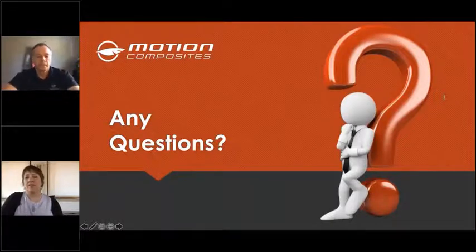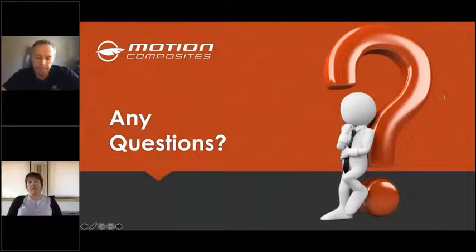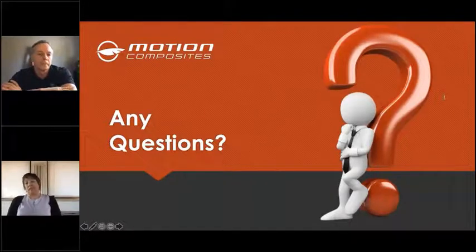Ralph, yeah, I see that question from Ralph about advantages in caster selection for use with active power assist users. So I think it depends on what type of power assist. You're right, if they're using like a SmartDrive or something like that, you might want to look at a wider caster, maybe sometimes a bigger caster if you can. Now in Europe where I'm at, they use a lot of front end add-on bikes that actually lift the front casters off the ground. So then you don't really have to think that.